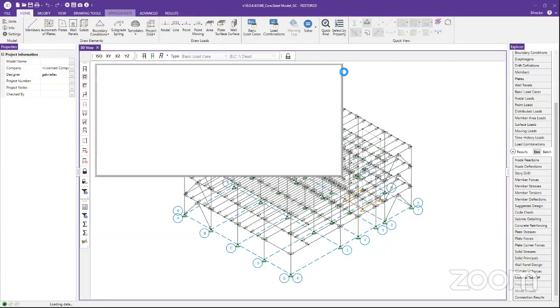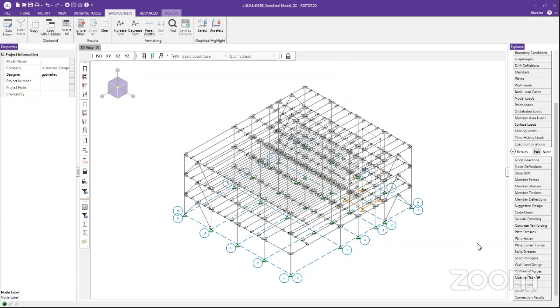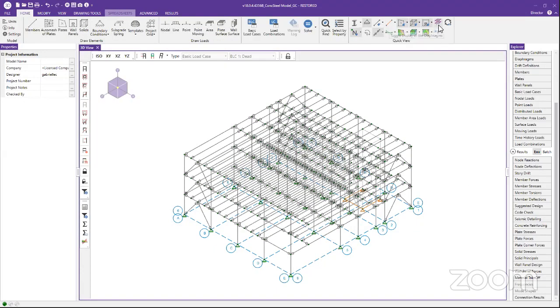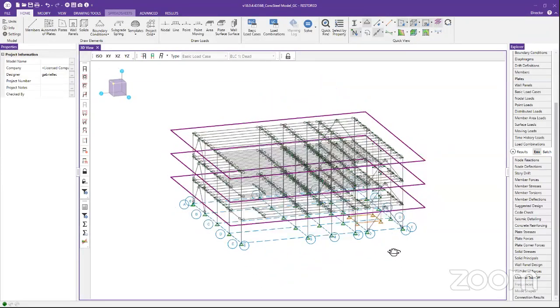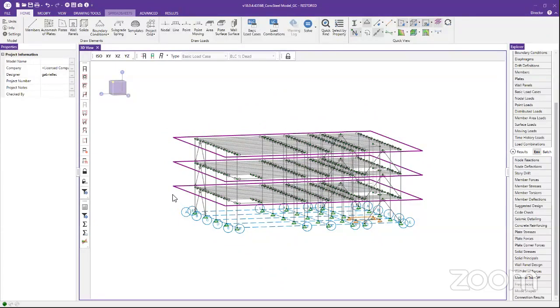One thing I forgot to mention, and it's good to talk through, is that we have our diaphragms on the screen. Diaphragms help to distribute the loads laterally. That would be one of the most important pieces to have when you're talking about RISA-3D with lateral loads: you're going to need some kind of a diaphragm. What this simulates is the building. At each floor level, we would have framing, maybe a concrete deck or metal deck or something that's going to tie this area together. And in this case, rigid. That means that it's fully rigid.